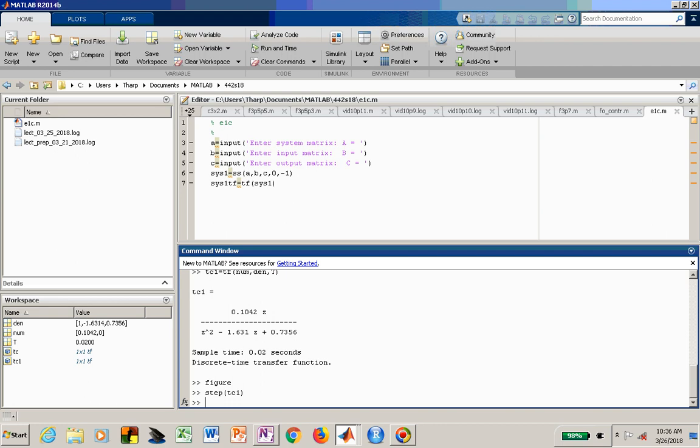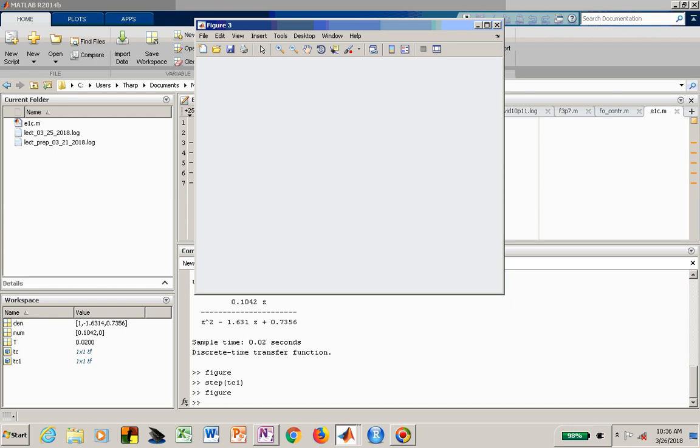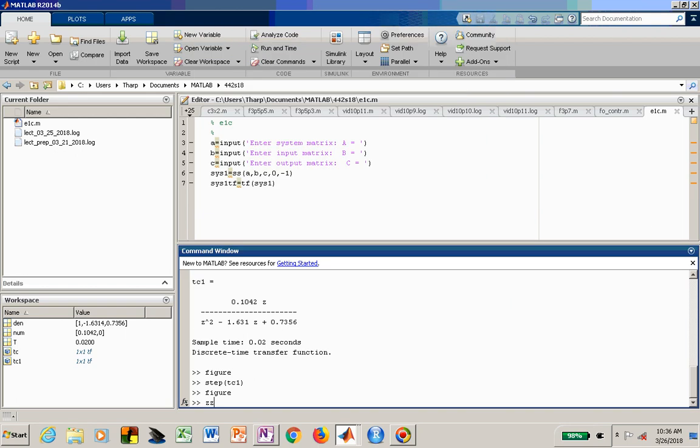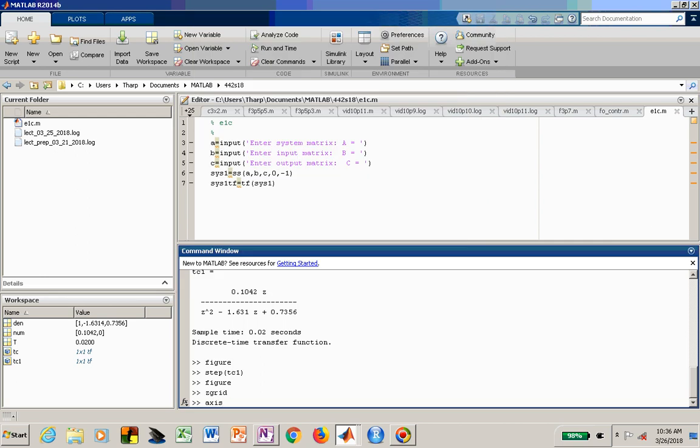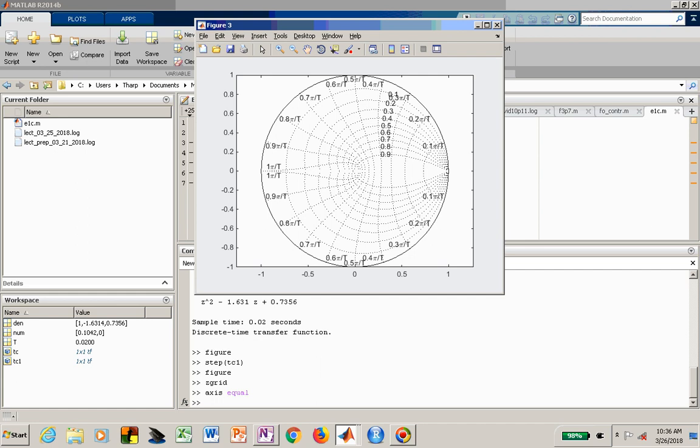Now, in terms of helping you plot things when you might have specifications in terms of radius, damping ratio zeta, or maybe even natural frequency, let's look at what we can generate from within MATLAB. We can generate a figure that we can print out and use to help us pinpoint locations in the complex z-plane. Here's the z-plane. It looks a little bit distorted, so let's make the real and imaginary axes equal so that our angles are actually valid.